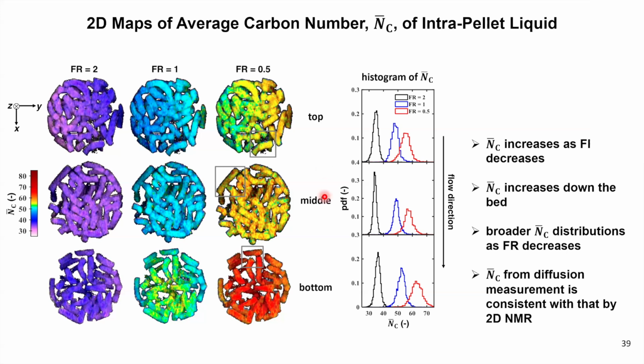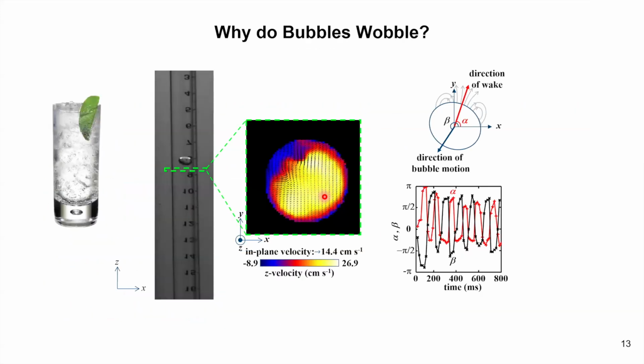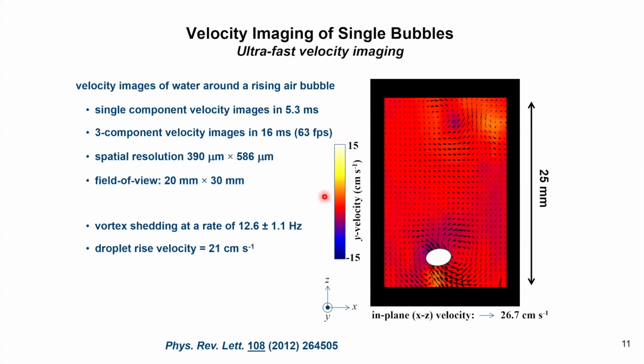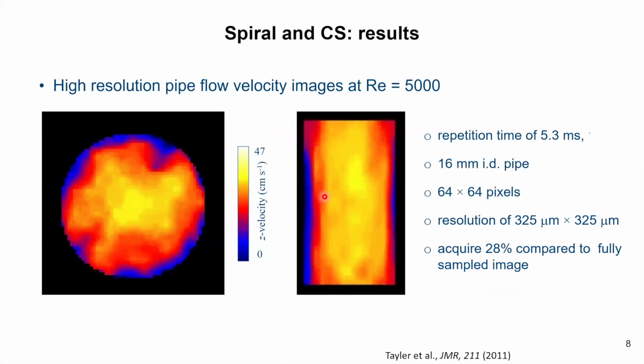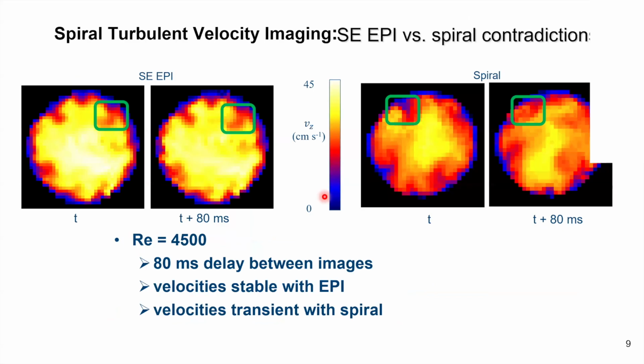I have a question there too. First I thought, how can you measure turbulence if you need to average signal, if you need sinus style, but you don't do sinus style, you do snapshot. I understand that, but one snapshot is only one velocity component, right? Well, I would argue that three components are still one snapshot. So it takes three times as long, sure, but the requirement is that the time is short compared to the changes. Therefore it becomes a snapshot.